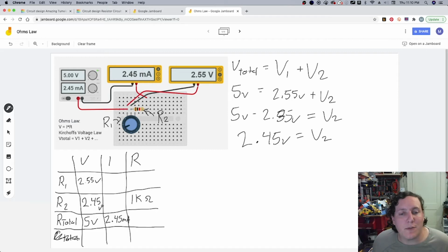And we're able to go ahead and decipher a little bit more information. Now, another thing to consider is that our current has to be equal. We kind of skipped that part when we were analyzing our circuit, but it's important to remember that in a series circuit, current stays the same. Whatever force the electrons are pushed through the first resistor, the first LED, it's going to be the same as it pushes through every single other component in that series circuit.